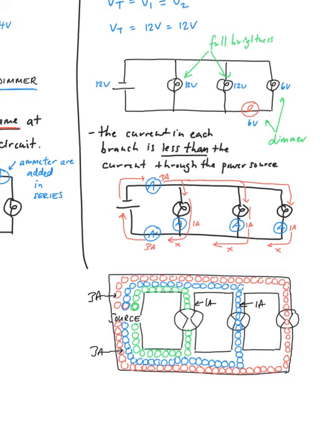This location is 1 amp, this location is 1 amp, or if I measured on the other side of the load, it would only be 1 amp, because in this entire outside circuit, there is only 1 amp available and flowing through it. But when you come back together now in this section, now you've got this guy plus this guy, I've got a 2 amp service. And then over here, I've got myself back to being a 3 amp service as I head back towards the battery.